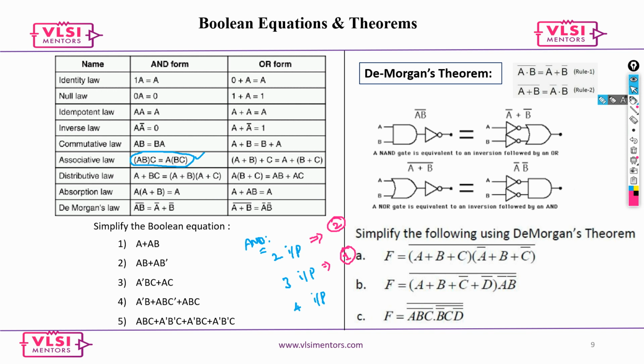So if you ask me, I would use the three input AND gate over the two input AND gate, because two input AND gates would cost me two stages, a logic level of two, one after the other in series. And the placement of these matters too. So using three input gets rid of one level of logic.